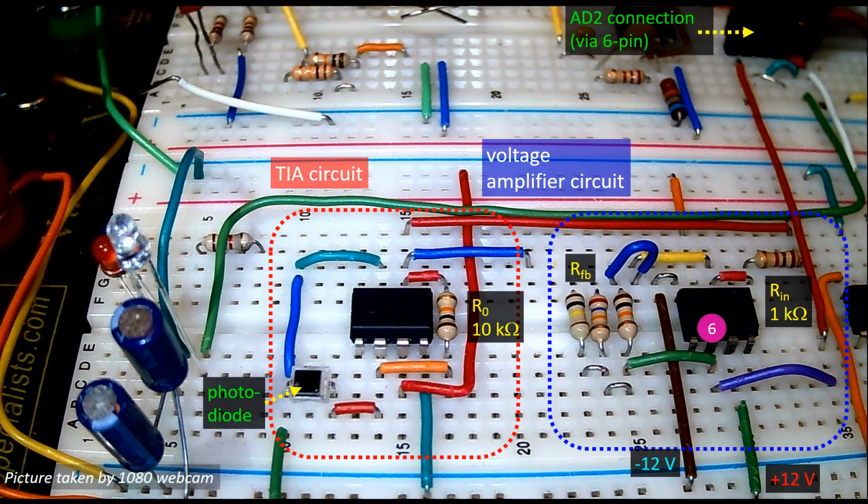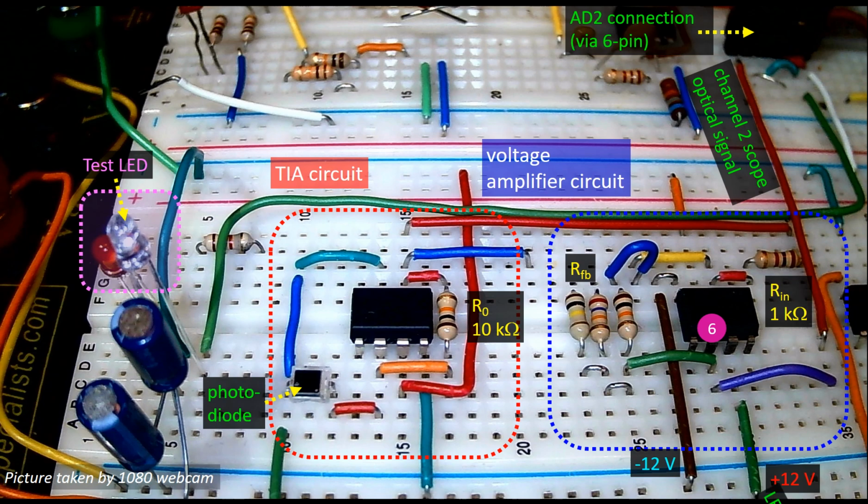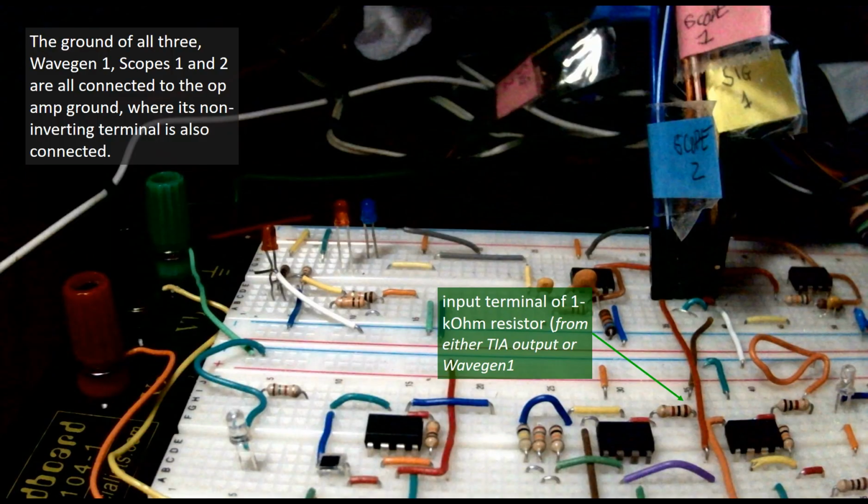Pin 6 output of the voltage amplifier is connected to a scope channel, shown here as channel 2, but either channel 1 or 2 is fine. In order to test the optical receiver circuit on board, a test LED is put close to the photodiode as shown in the magenta enclosure. The LED is driven by the signal generator of the AD2, which is via a green wire as shown in the figure. This picture shows a different view of the AD2 connection to the circuit.